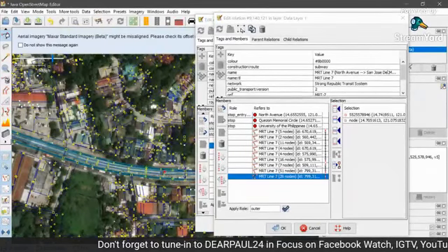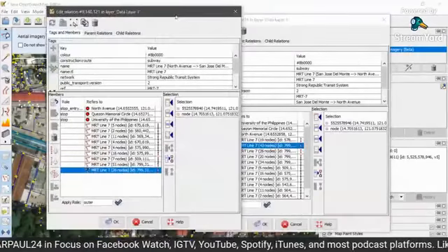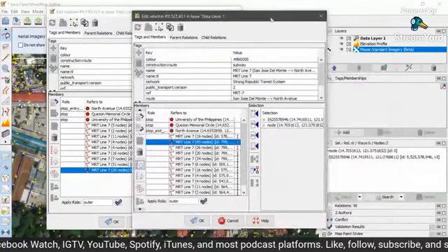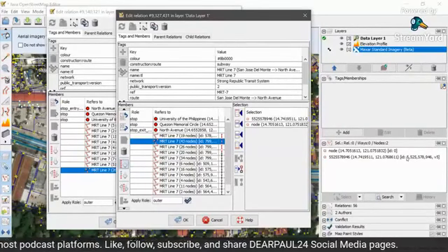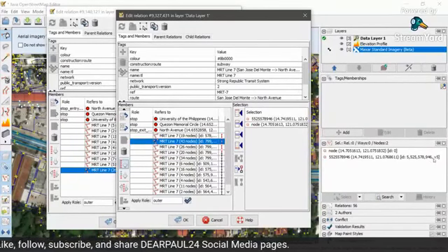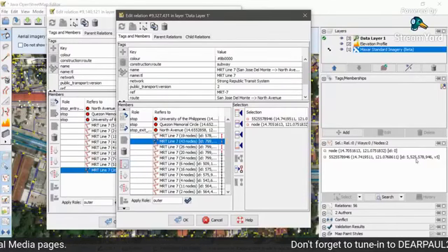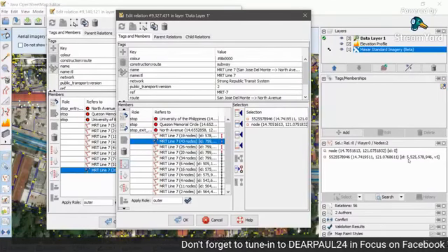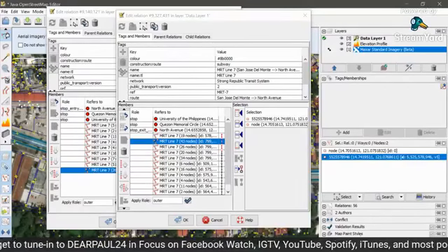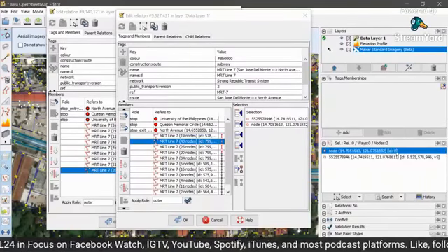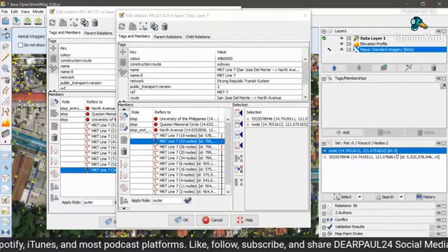Make sure that if you're going to transfer the node with the node number like this one, node ID 5,535,000,000 something, just make sure that the ID of another one is set to 0 before you press merge.